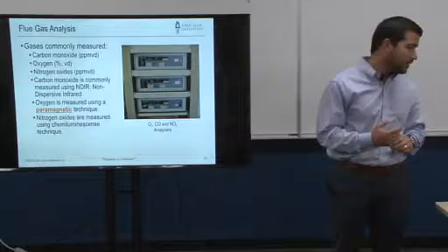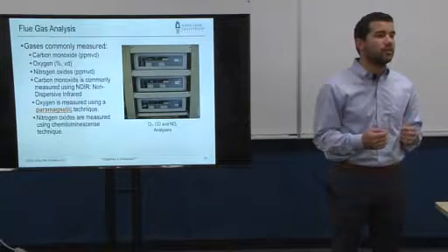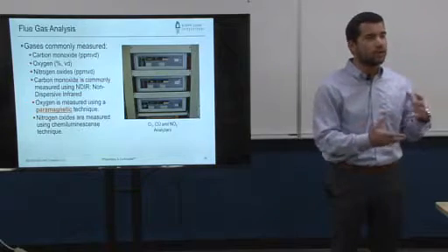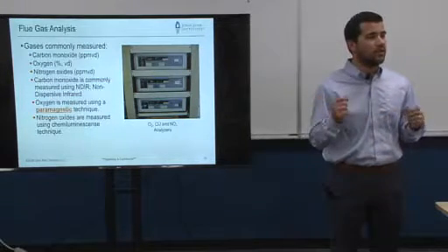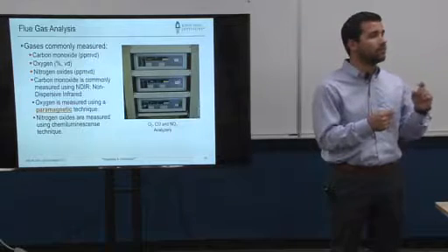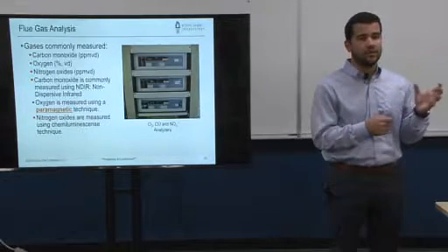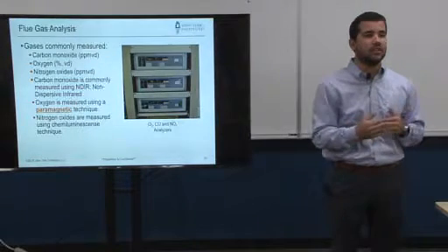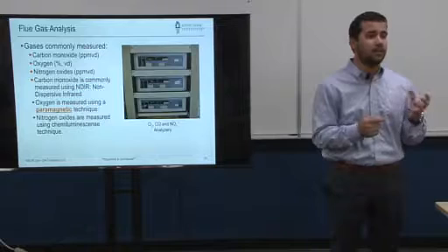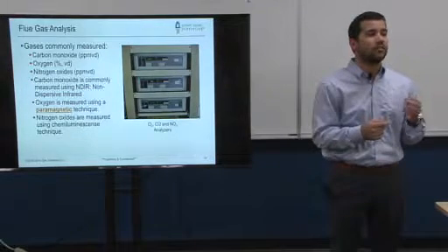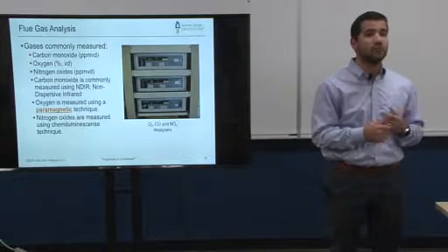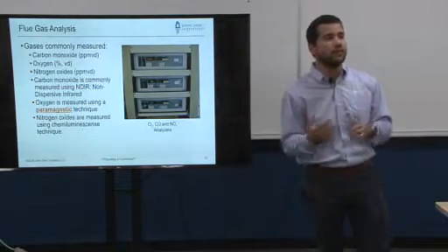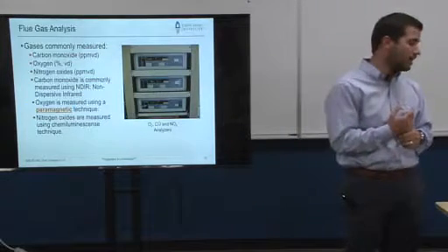And the CO, the way to measure CO, really what you do is you get the flue gas sample, and it's actually conditioned, so it's all dried out, and it gets through this analyzer, and you actually shoot a laser at a particular wavelength, and you try to measure that beam again, and you understand the amount of light that was absorbed, and through that you can understand what is the CO occupancy on that flue gas. And so it'll give you a number in ppm, so it'll give you a volume number of CO of that particular flue gas.